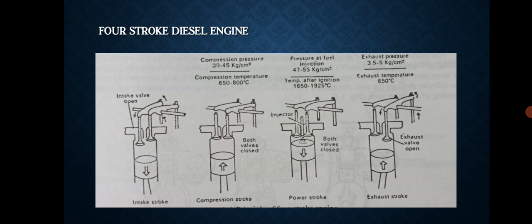During the fuel injection period, the piston reaches the end of its compression stroke and commences to return on its third consequent stroke, that is the power stroke. During this stroke, the hot products of combustion, consisting chiefly of carbon dioxide together with the nitrogen left from the compression air, expand, thus forcing the piston downward. This is the only working stroke of the cylinder.